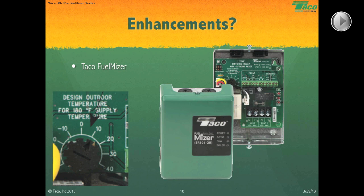At 0 degrees, I would actually have something less than 180-degree water, which is the opposite of what I want. So if you want to be quote-unquote safe, if you're nervous, you don't like 0, but you want a little extra, turn it up to 10. Now you're saying, okay, at 10 degrees outside, I want 180-degree water. Just so you understand and don't make the mistake in the wrong direction. Okay. So that's the hard part as far as setting up your system.